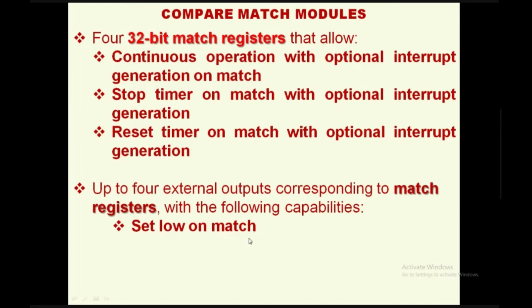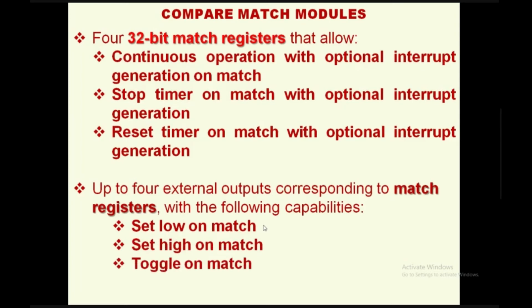That pin I was calling the PWM pin. Whenever there is a match, we can set that pin low, set that pin high, or toggle that pin. Or we can do nothing on match. These are all the facilities or features available in the LPC2148 timers. Based on the application requirement, the design engineers can make use of these features. Okay, so that is the idea here.